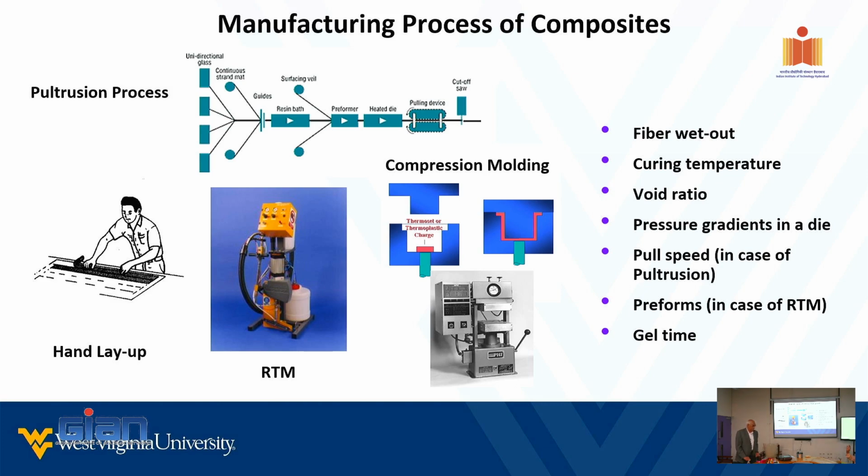And the smallest? The smallest are like 1/8 of an inch, but we do not use. The ACI code does not recommend anything less than a 1/4 inch. But we did produce 1/8 inch, like fishing rods, for example. Like stirrups, what is the comparison for stirrups? Yeah, for stirrups, again, the code does not allow us to go beyond 7/8 inch.